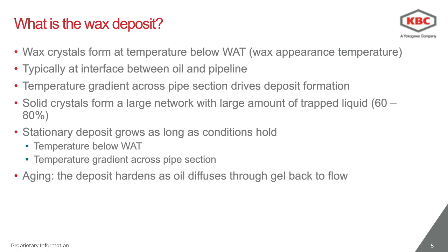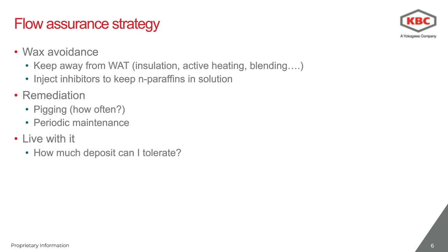Another phenomenon called aging may occur in the deposit as the deposit keeps growing, and as time goes by, a counterflow starts depleting the deposit of oil. So the trapped oil starts to diffuse back into the main flow. As a result, the deposit will tend to harden and become more difficult to remove from the pipeline. This phenomenon is called aging, and it normally happens at a different time scale from the deposition itself.